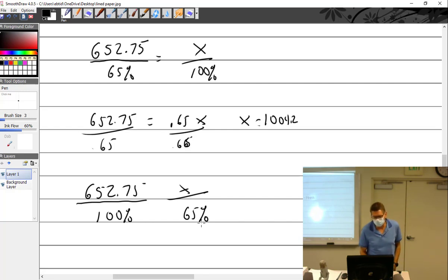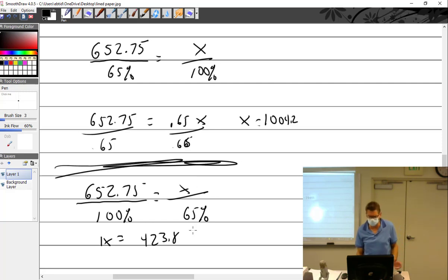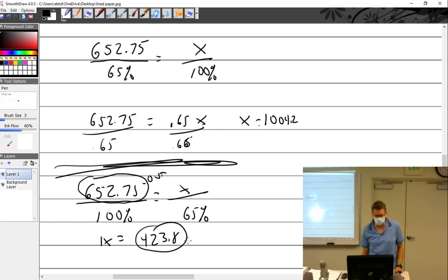The reason it would not sound right, or you can go with it, then you get 1x equals 652 times 0.65 equals 423.8. Everybody know where I'm going with this, right? So I did this down here, a whole other thing, trying it all over again. My two numbers now are 652, my output, and my input then is 423.8 watts. How efficient is that motor?